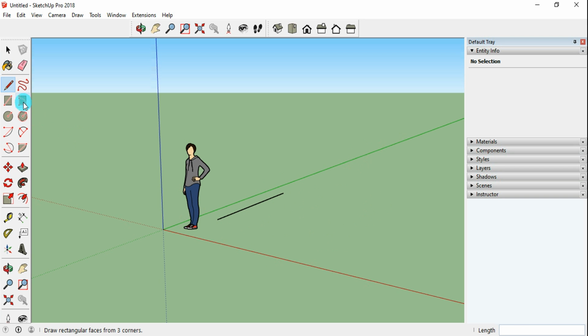So whatever tool you are going to choose there, if you want to get some command prompts like how to use the tool, etc., you can observe the prompts at left side of the screen, okay. So say for example, I'm just going to select the rectangle. It is saying to select the first corner, wherever you want to give the first corner and opposite corner, okay.